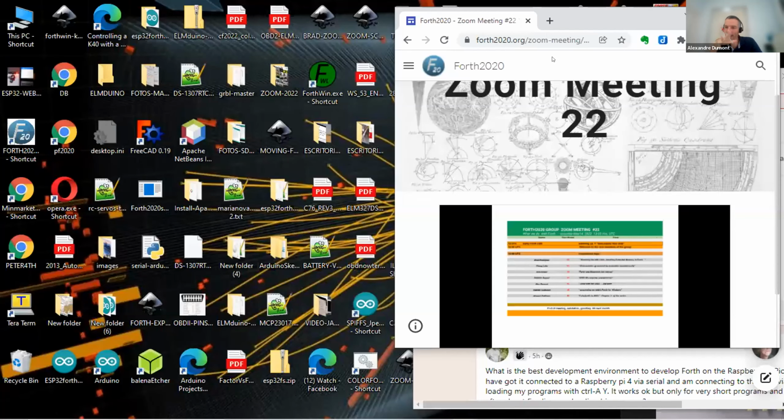Fantastic. Sorry? No, it's not an 860. No, it's a R65C19, I think. Yeah, it's a different computer. It's like a version of the 6502 with new registers. It's still 8-bit, but there are new registers, and there are 16-bit registers. One I think is I, and the other is W. And it seems interesting for FORTH.